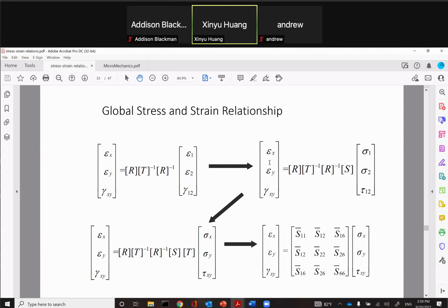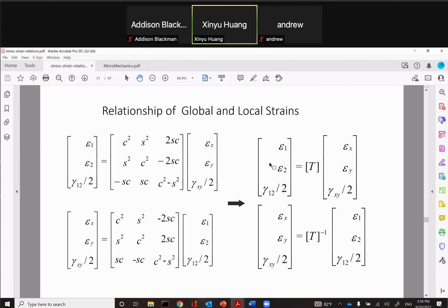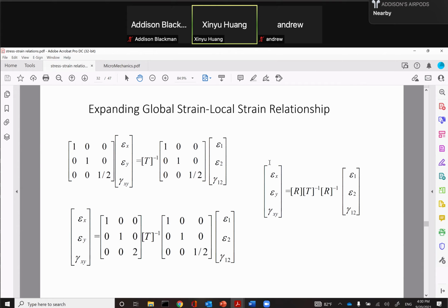So basically, in the code you write, you would start from your fiber orientation, and you define your layer properties. Then you identify these matrices. Our matrix is this matrix right here. It's a utility matrix to go from engineering strain to tensor strain.